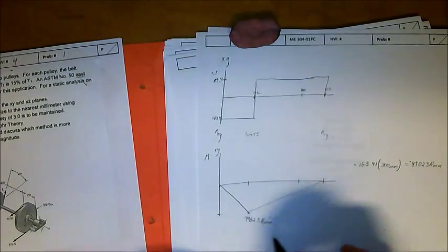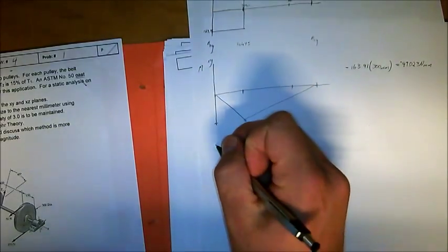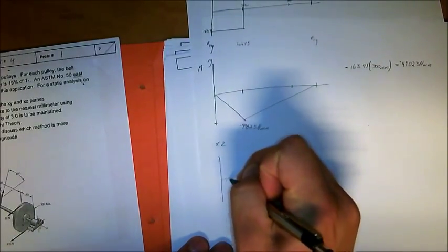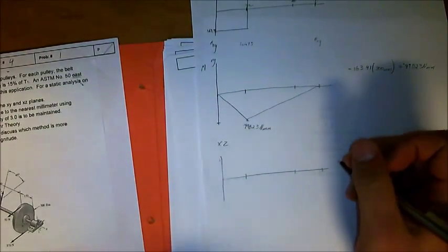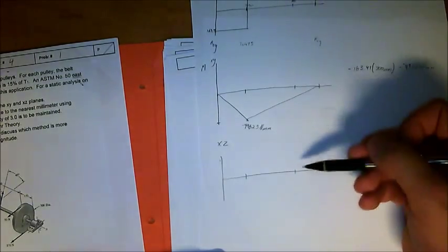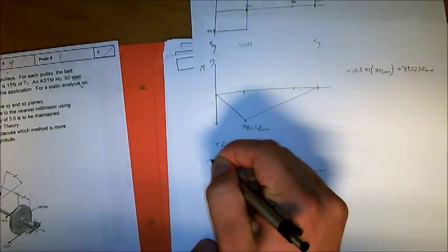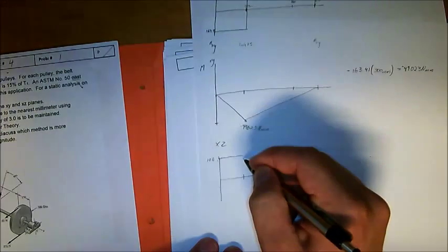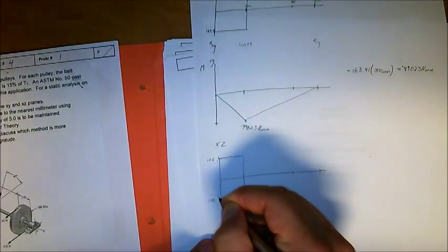Okay, so moving on to the XZ plane. We start out with the basic shear diagram, 300, 400, 150. And you can see how these all line up. This just makes it easier doing the shear moment diagrams because you know which point it is all the time. So we start out with ROZ, which is 106. That goes over to there. Then we have the negative T cosine 45, which takes that down to negative 146.35. I know I'm going through this kind of fast, but you can get the basic idea of what happened up here and then just apply this down here with the new reactions.